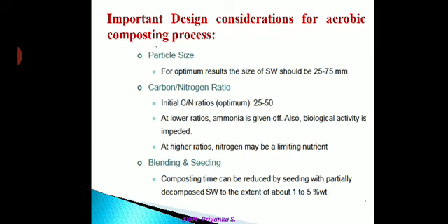Here the proper blending of carbonaceous and nitrogenous material for a proper C/N ratio is very much essential. So the materials which are too wet or too dry for good composting can be blended in a proper proportion to achieve the optimum moisture content. So what is meant by seeding? Seeding involves addition of a volume of microbial culture sufficiently large to effect the decomposition of receiving material at a